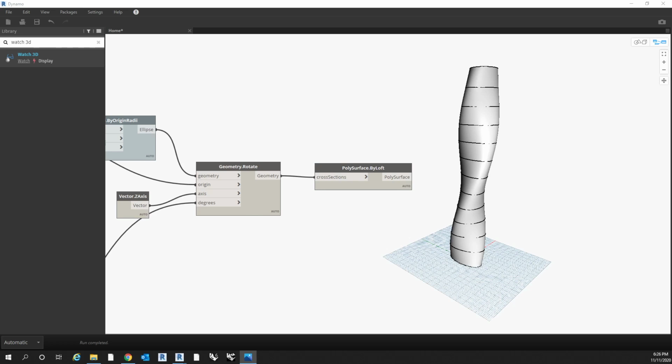So now, what can I do with this? Well, I can try and bake it and use it as a conceptual mass. But that's kind of ultimately what this geometry is going to allow us to do. We can push this a little bit further to really develop and create Revit elements from this, and actually start to set up our Revit project based around this. And since it is fully parametric, we can manipulate and adjust certain parameters, and have the Revit project and the elements that we attribute to this geometry live update as well.